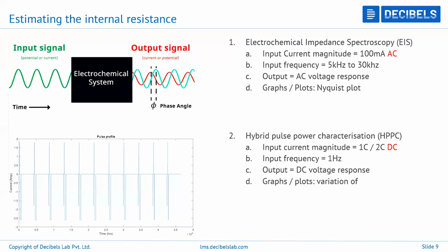That is correct. Then for the other one: should the internal resistance be measured in AC or DC? The answers seem to be very interestingly distributed. In reality, it is not a standardized fixed way that it should be only AC or only DC. Usually it is both.